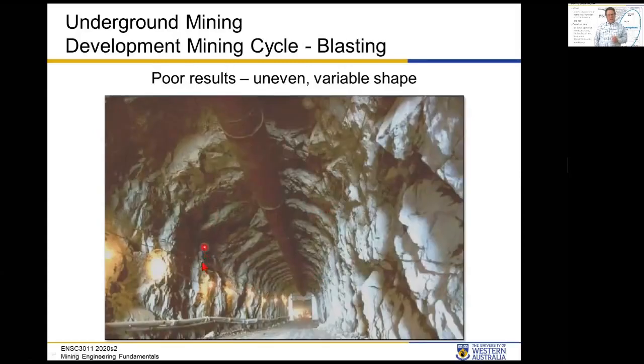You can see how the shape, the size has changed at each drill advance. So there's one advance, and then they've drilled again. It's changed section, and it looks like quite a few boulders. I wouldn't be too comfortable walking down there. I'd be keeping an eye on the roof, particularly as there's no ground support, no mesh, no shotcrete.